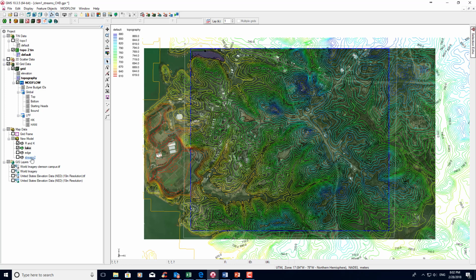And then we have streams, and this is going to be really the new step. So what we're assuming is that where we have the stream and there's surface water there in the stream, that surface water is at the same hydraulic head as the aquifer would be at that point. So we'll assume that the stream is like a surface exposure of the water in the aquifer.